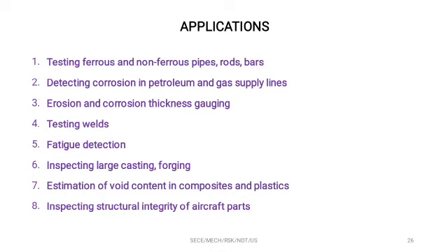When you come to applications: testing ferrous and non-ferrous pipes, rods, bars, detecting corrosion in petroleum and gas supply lines, erosion and corrosion thickness gauging, testing welds, fatigue detection, inspecting large casting and forging products or parts, estimation of void content in composites and plastics, and inspecting structural integrity of aircraft parts. So these are the wide applications of ultrasonic testing.